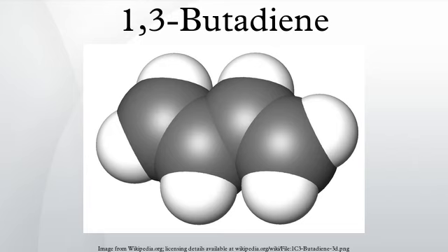Most butadiene is polymerized to produce synthetic rubber. While polybutadiene itself is a very soft, almost liquid material, copolymers prepared from mixtures of butadiene with styrene and/or acrylonitrile, such as acrylonitrile butadiene styrene, acrylonitrile butadiene and styrene butadiene, are tough and/or elastic. SBR is the material most commonly used for the production of automobile tires.